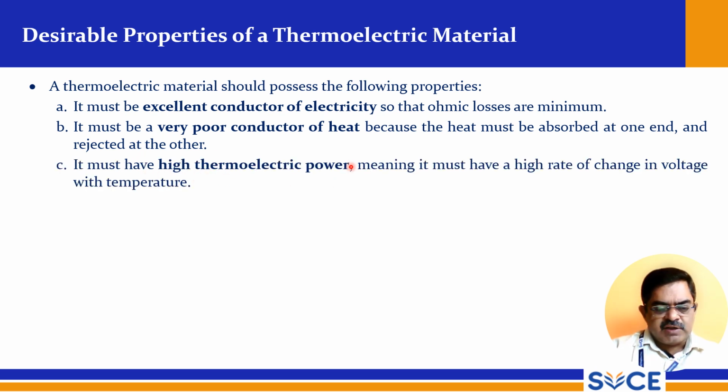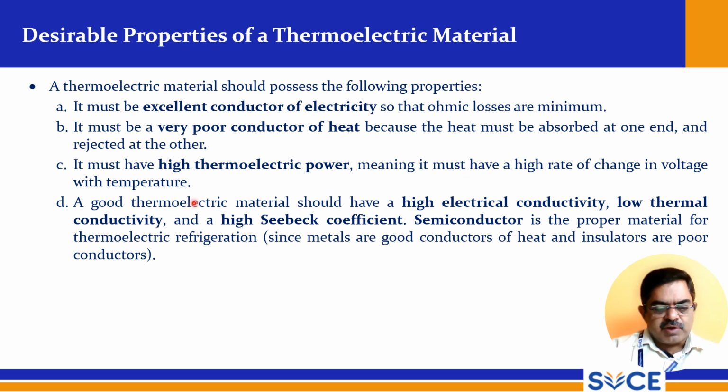It must have high thermoelectric power, meaning a high rate of change in voltage with temperature. A good thermoelectric material should have high electrical conductivity, low thermal conductivity, and a high Seebeck coefficient. Semiconductor is the proper material for thermoelectric refrigeration, since metals are good conductors of heat and insulators are poor conductors. So this is how this property should be maintained.